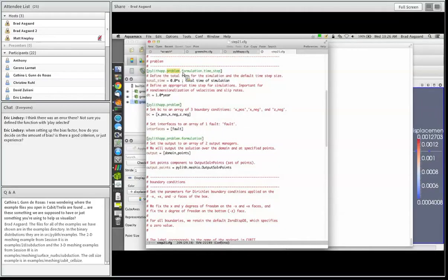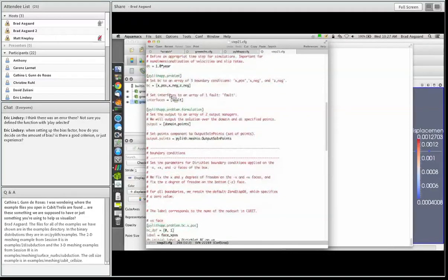For the faults, all we need to do is specify, since we've already specified our impulse amplitude, so it just has an ID of 10, the label fault. The mesh is a hex mesh, where this is the fault, one dimension lower. Hex means Lagrange family of elements, so quads, lines, and hex elements are FIAT Lagrange. Cell dimension 2 for our quads.